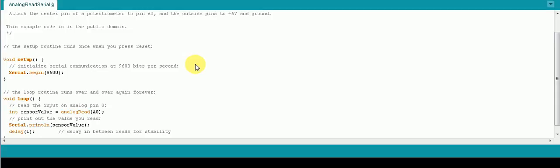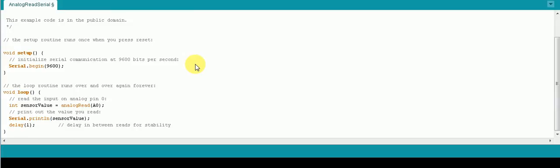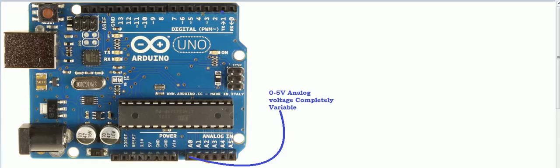Now that you have understood the theoretical concept of why we need an ADC in a microcontroller, let us take you to the program. First of all, we have to understand there is no need to initialize an analog pin for an ADC. So straight away we go to the loop. In this loop we have defined a variable, sensorValue, that reads the value of analog signal A0.